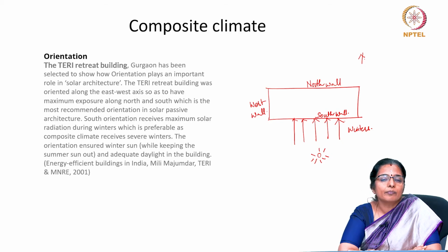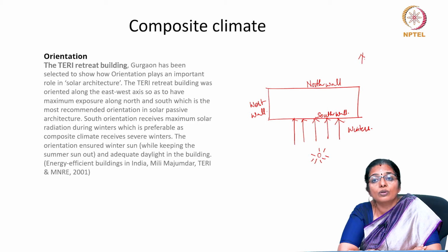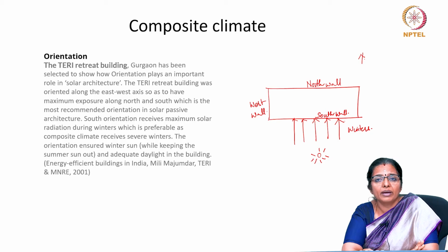Hygienic reasons, meaning algal growth and fungal growth, have to be curbed. Otherwise, mold growth can become a big problem. Shelter should be provided from the winter winds, and the buildings are preferably rather compact. However, because of the conflicting climate conditions, you have two kinds of climate condition, so several solutions are possible depending upon local topographical conditions and functional requirements.